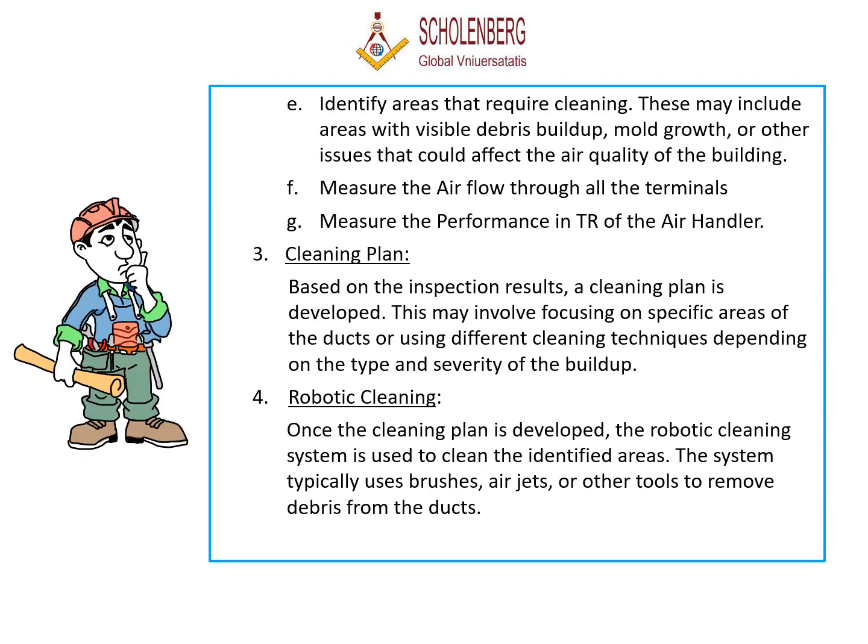E. Identify areas that require cleaning. These may include areas with visible debris buildup, mold growth, or other issues that could affect the air quality of the building. F. Measure the airflow through all the terminals. G. Measure the performance in TR of the air handler.